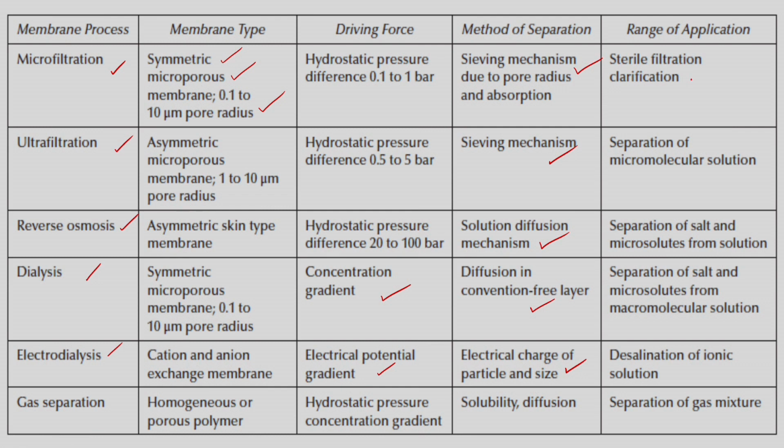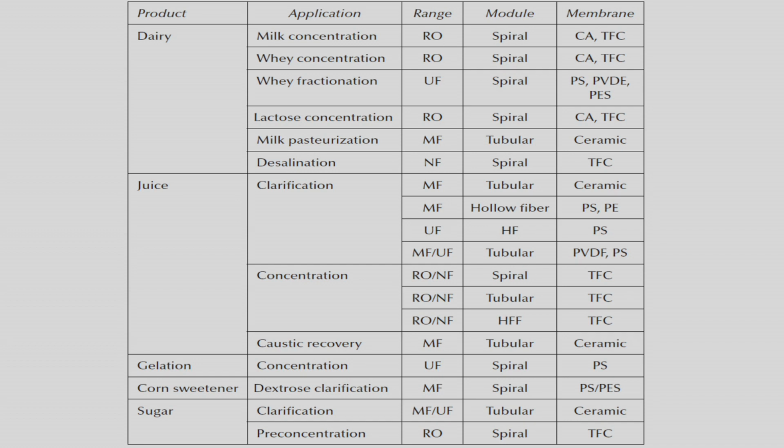Microfiltration is used for sterile filtration and clarification. The separation of macromolecular solution is nothing but ultrafiltration. Separation of salt and microsolutes from solution is reverse osmosis, and separation of salt and microsolutes from macromolecular solution is dialysis. Desalination of ionic solution using an electric field is electrodialysis. Separation of gas mixture comes under the category of gas separation, but anyway we are going to concentrate only on the first five.